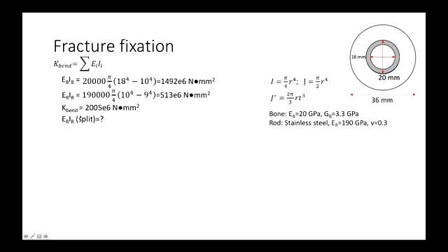Yeah, the split where we don't have any little cross section in there. How would we calculate that? So the question is, would having a split through the centre of the rod make it weaker in bending? Or would it be the same? So the answer is it's the same actually.